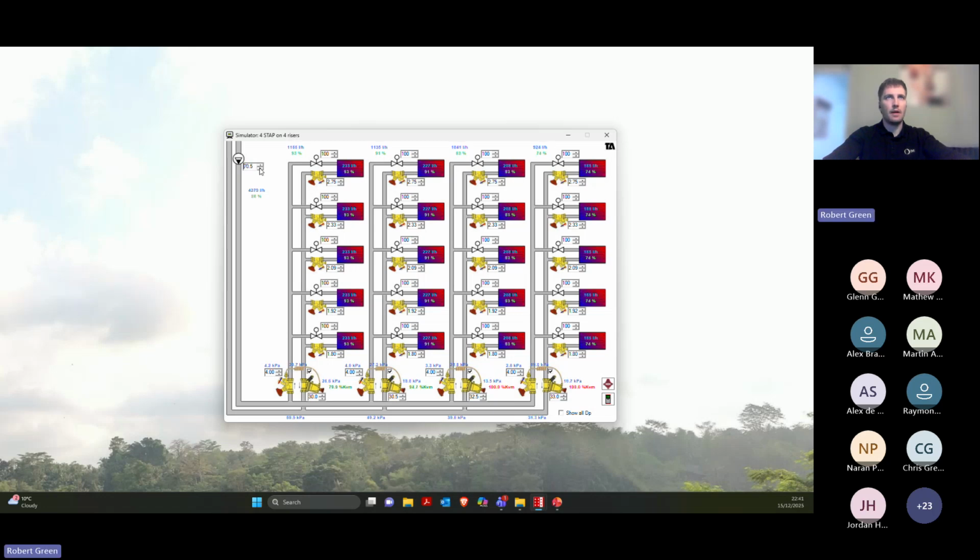So we now set my pump at minimum speed. And as you would expect, at minimum speed of the pump, we no longer have a balance correctly in the system. And you can see that actually these first two differential pressure controllers are 100% open.